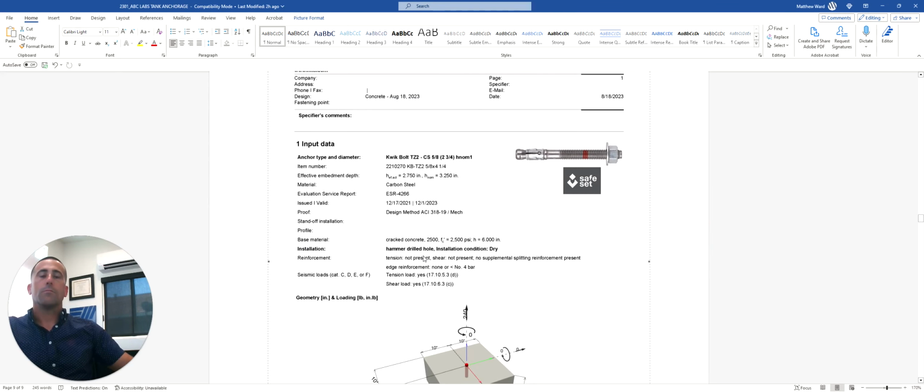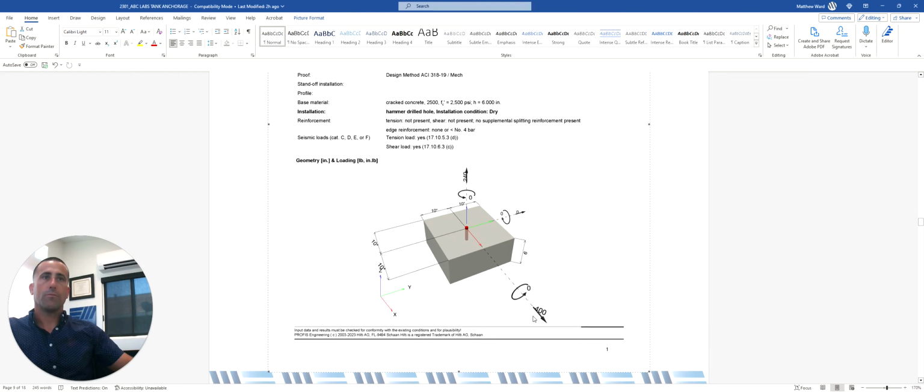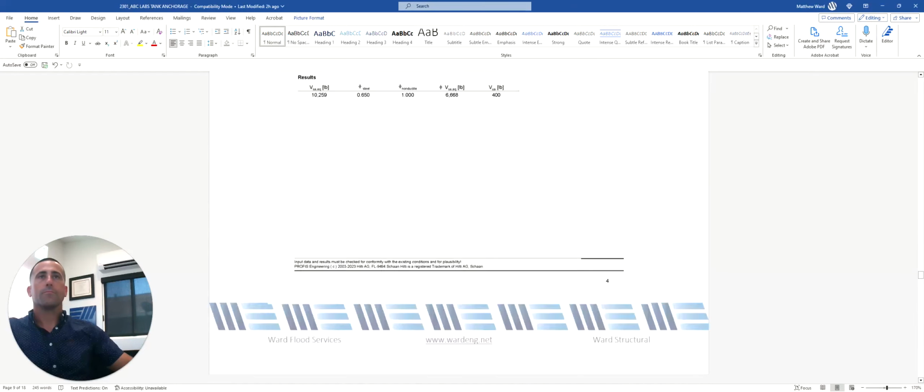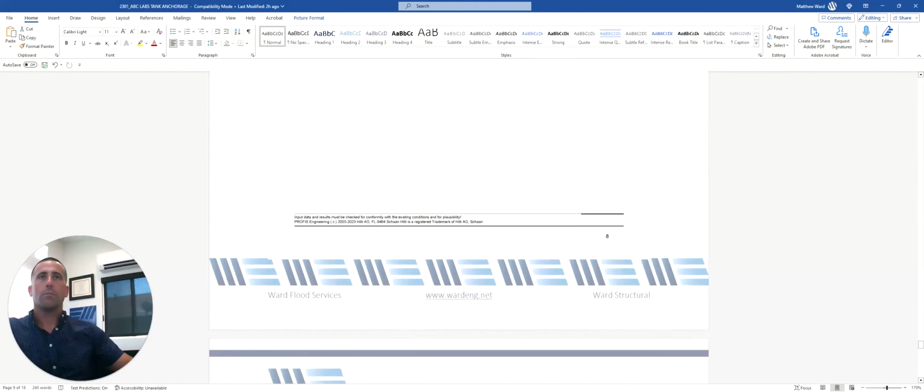and here's my report. And so, as we stated, 5/8 inch anchor bolts with 2 3/4 inch effective embedment, and a nominal embedment of 3 1/4 inch embedment, which we'll get to more once we get to the CAD file. But here's our report showing our loads: 400 pounds in the lateral direction, 240 pounds pulling up. So now our Hilti report is in there.